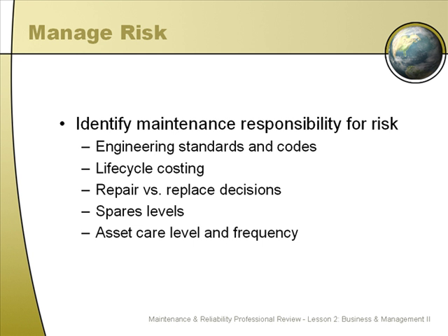For example, many facilities, as they become more proactive, will find a higher usage of things that are consumable, such as filters and routine tools that you use for preventive maintenance, and much fewer uses of things like bearings and seals and larger items that could be purchased as a planned job rather than kept on hand for breakdowns. Once the breakdowns disappear, you don't need those parts any longer.